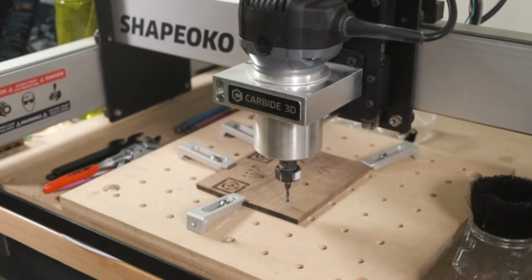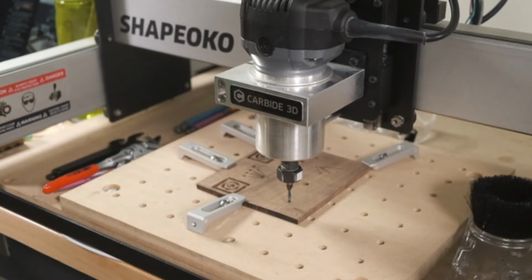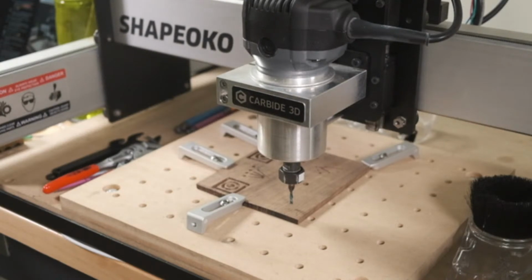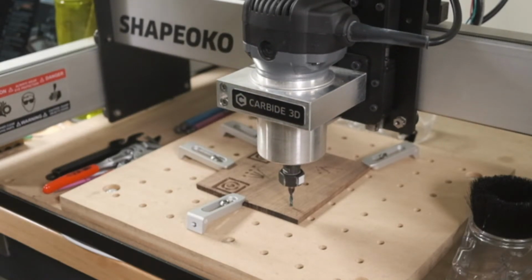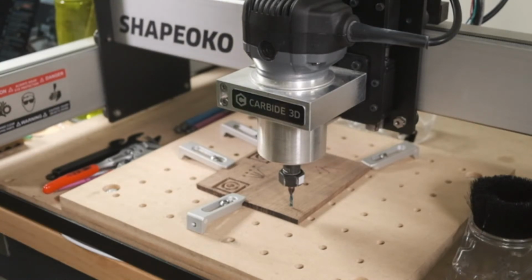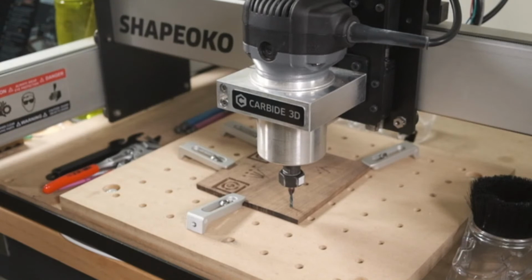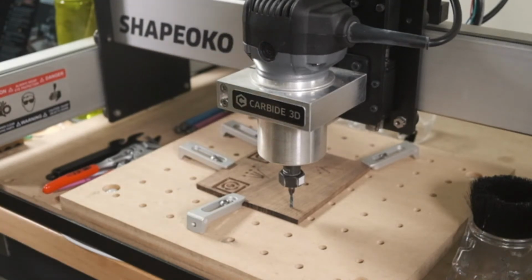If you're machining aluminum and you get a gray coating of aluminum dust, and if the aluminum itself is smeared on the end mill, if you drop it into a little bath of sodium hydroxide or lye, that will actually dissolve the aluminum in a couple minutes without damaging the carbide material of the end mill.